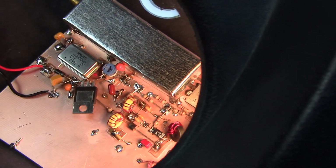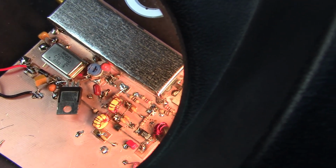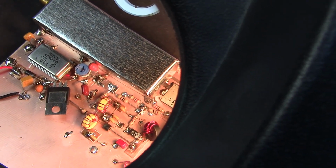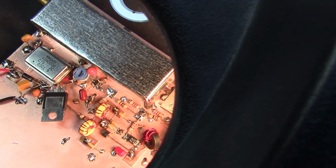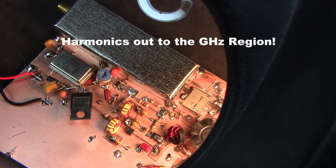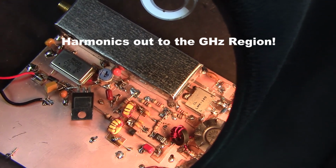As you can see, I've piled up a couple of chip caps and a tantalum capacitor on the positive pin, the VCC pin, pin 5. It really needs good bypassing to ground because this thing is hot. It's got a lot of gain. You can see the potentiometer for the bias control on the front.